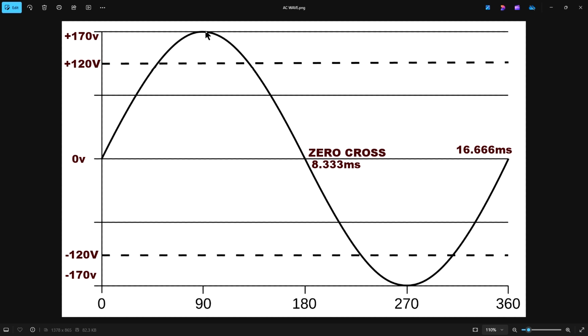So you can turn it on. You don't have to keep a voltage continuously on the gate. A literal pulse will turn it on. It'll stay on all by itself. Now, you don't hurt it by applying a gate voltage and leaving it there, but you don't have to leave the gate voltage there.